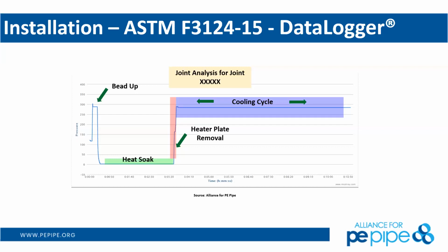So it's really, really critical. Another thing to consider, and the reason this graph is so important, is the open time of that plate. What if you're at minus 10 degrees or plus 80 degrees? It's really critical that we understand these curves and have these for your records. Usually the technician will label them as he goes along, so it really gives you that assurance. But if we see something different in this type of cycle to review, then you might want to question that particular fusion. And if it looks questionable, then you can cut it out and redo it.